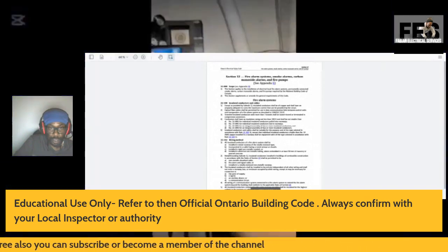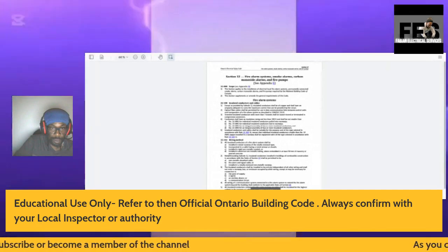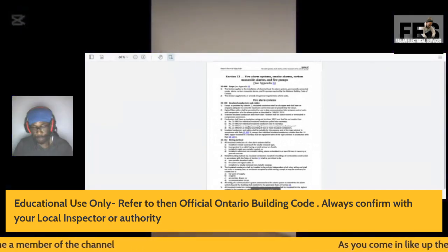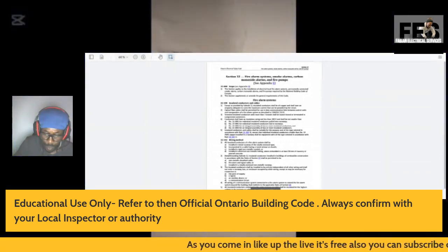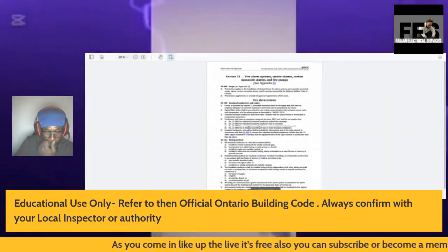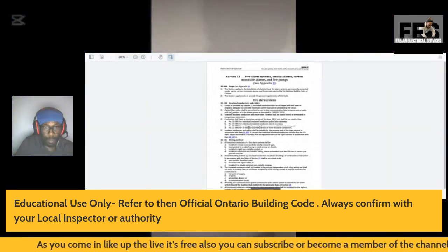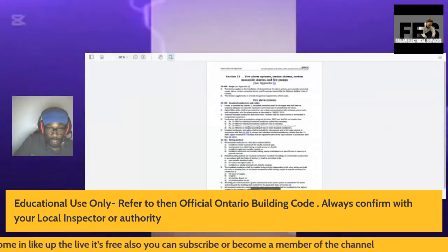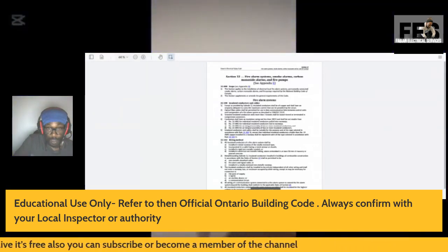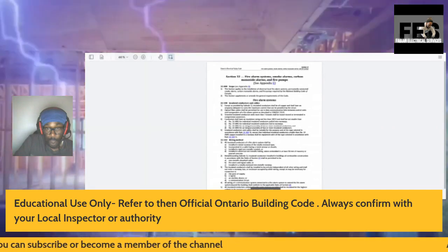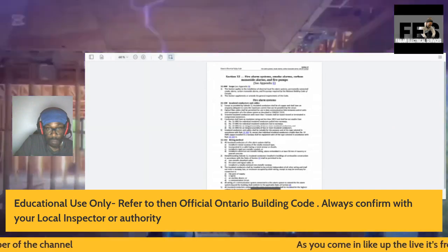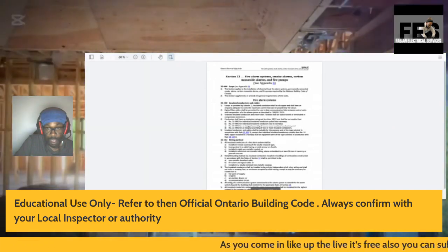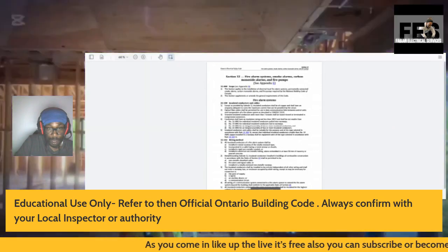Except as provided by Subrule 2, insulated conductors shall be copper and shall have an ampacity adequate to carry the minimum current that can be provided by the circuit.